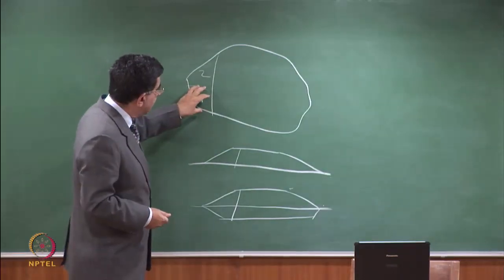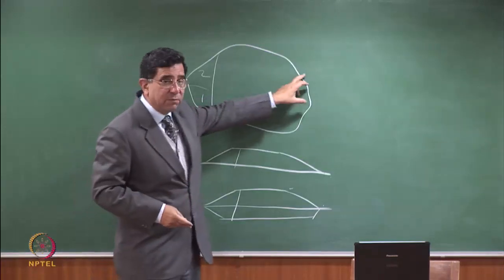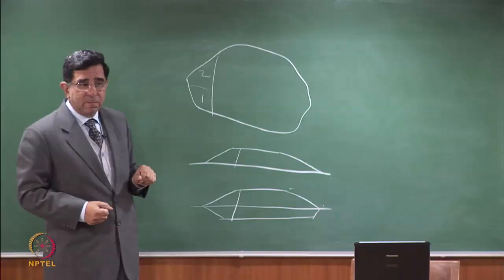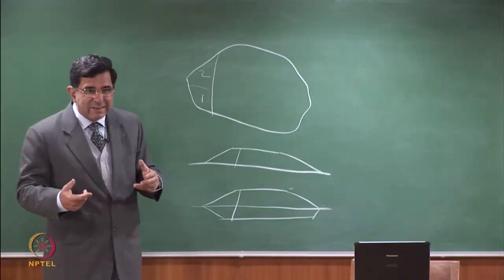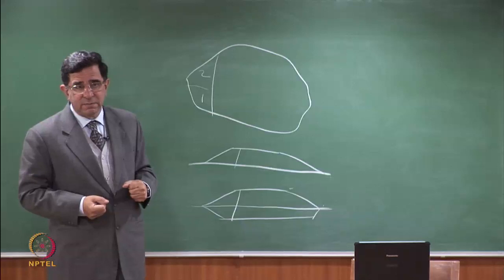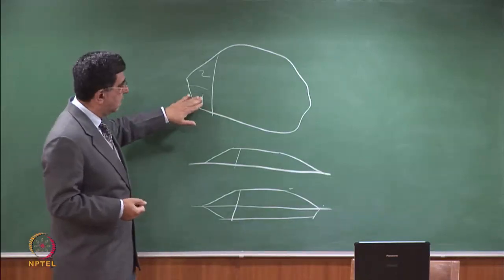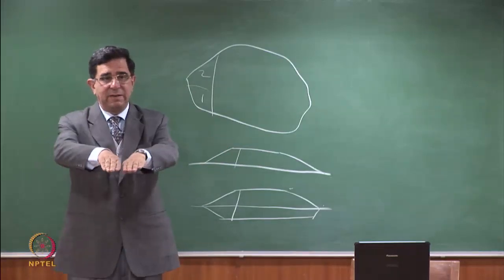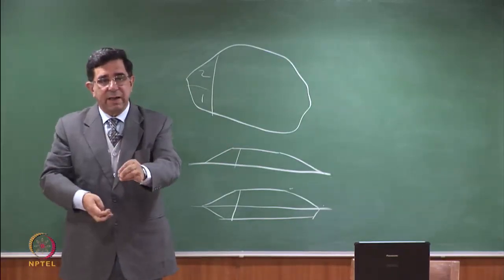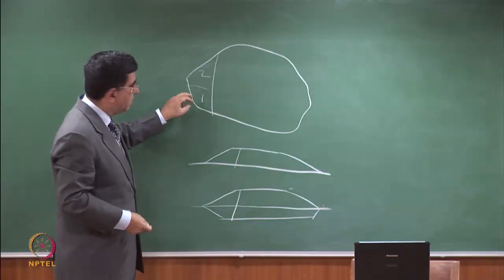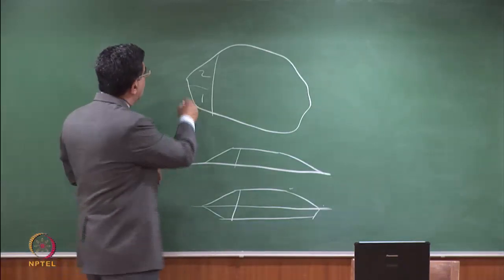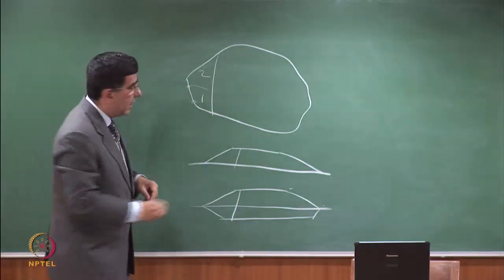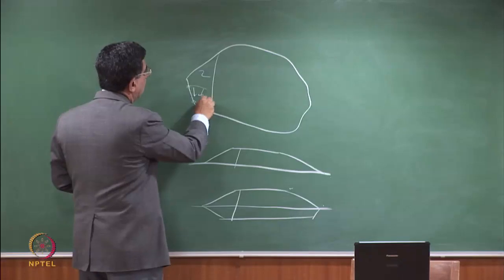So in now deciding that the leachate of phase 1 will not go somewhere far off and a well will be there in phase 1, where will you place it? Or a leachate collection point will be there, where will you place it? I can say, all right, this is my leachate floor, I'll make it like this. And I'll take the leachate to an edge. So it will be at an edge, but it can be any place, 1, 2, 3. So these are 3 locations one can think of, right? And water will have to flow, I mean leachate will have to flow.